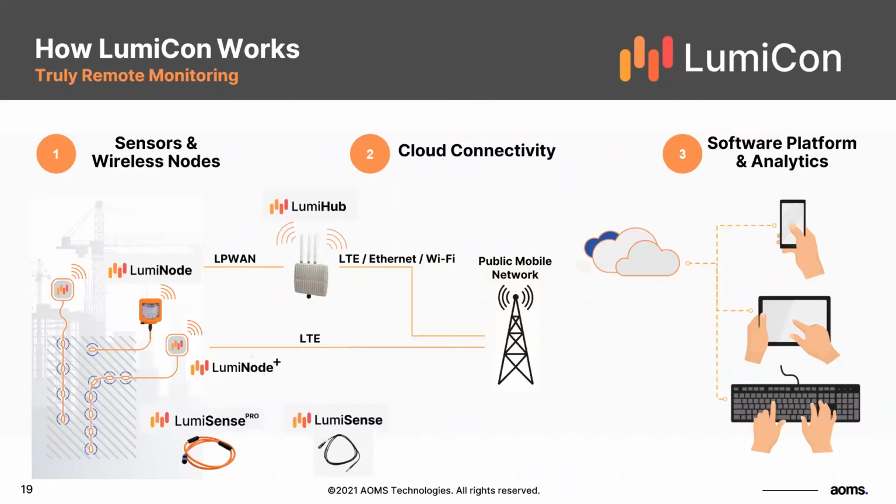First of all, we have a very interesting approach to monitoring the concrete, which is monitoring in a distributed fashion. As I mentioned, monitoring the curing of the concrete and the quality is important to do at different locations. You don't want to use only, for example, one sensor at one corner, or just one sensor at the core of the concrete. If you're dealing with concrete that is thicker than 8 inches, you want to make sure that you have sensors at different locations for monitoring purposes.